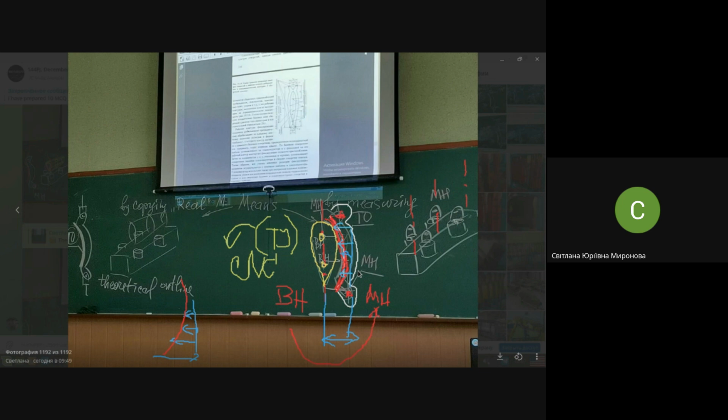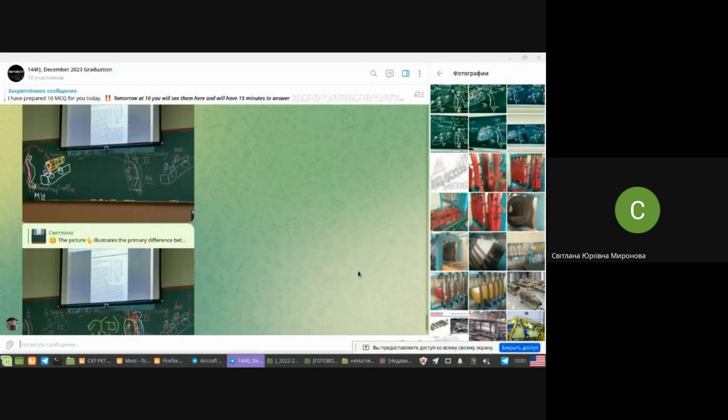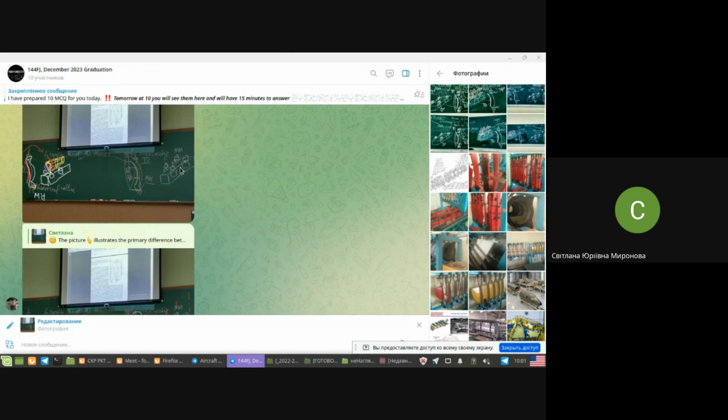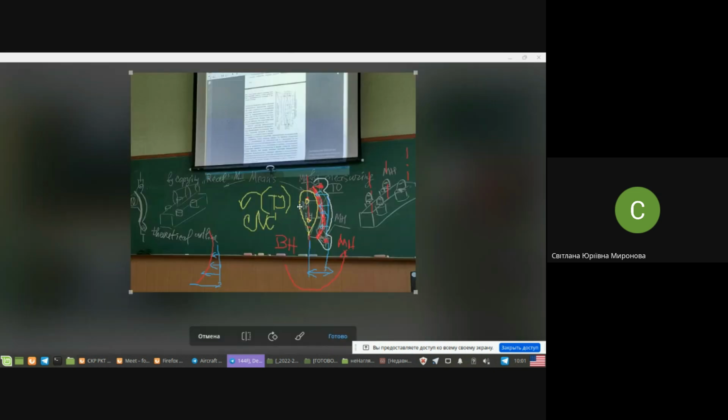And in order to provide correct placing of locators, we are forced to measure these mounting hole positions twice. On one hand, we measure the contour with respect to the mounting holes in locators. On the other hand, we are forced also to measure holes in forks.